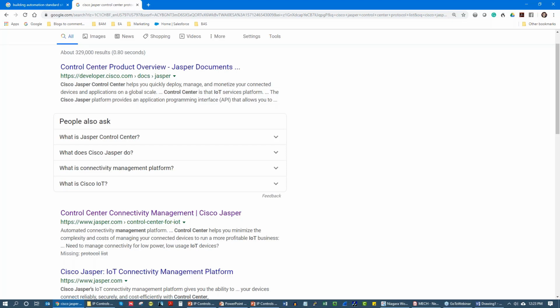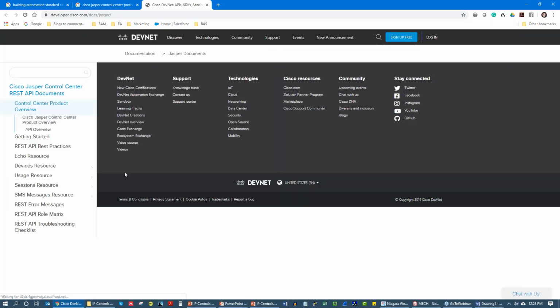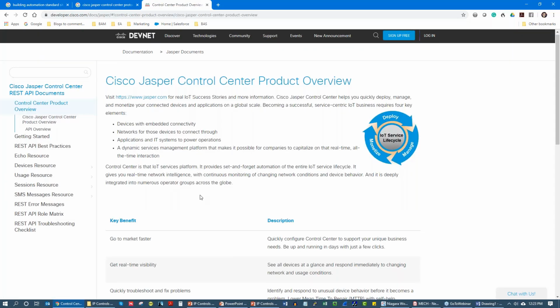Then I would create a consistent data taxonomy. So what am I going to name things? So I have consistent naming. And then it's just a matter of, if they support BACnet IP, pulling it in. I know I greatly simplified that, but if they don't support BACnet IP, that's going to be a headache because a lot of manufacturers do not support RESTful APIs.